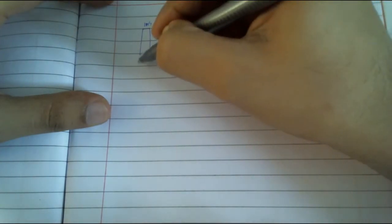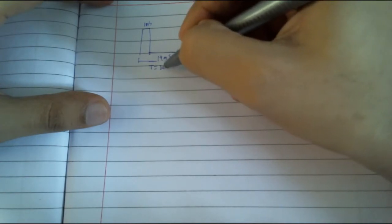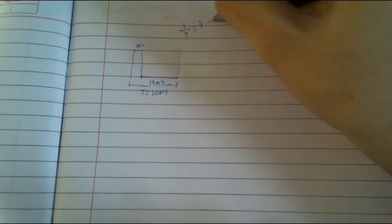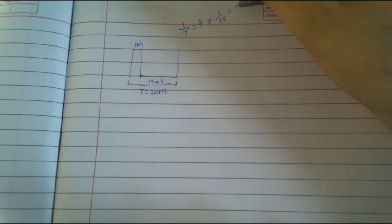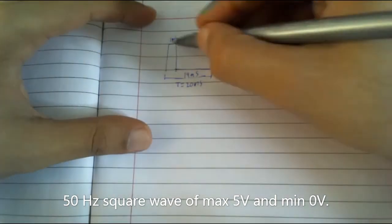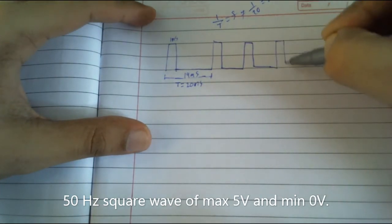So let us see the signals that we require to control the servo motor. We generate a 1 millisecond pulse followed by a 19 millisecond off time, and the total time T is equal to 20 milliseconds. 1 by time is equal to frequency, so 1 by 20 milliseconds is equal to 50 hertz. So we need to generate a 50 hertz signal in order to control the servo motor.